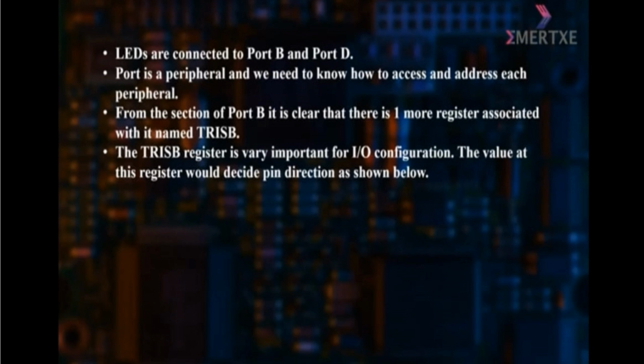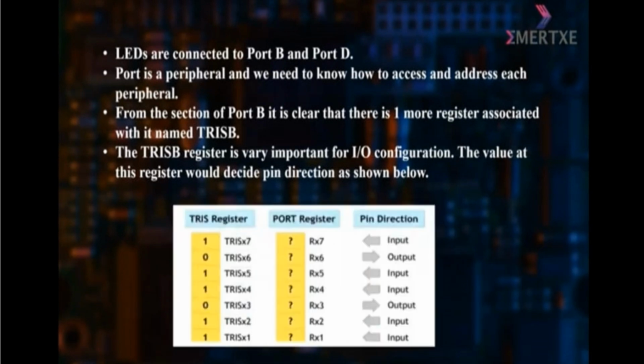The TRISB register is very important for I/O configuration. The value at this register decides the pin direction as shown below: TRIS register, port register, pin directions.